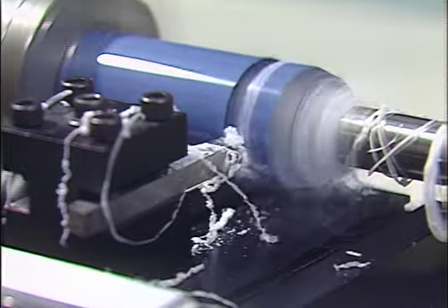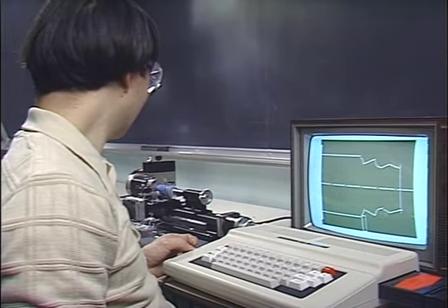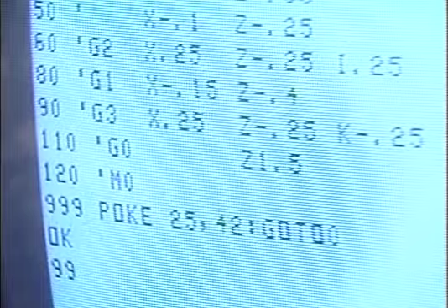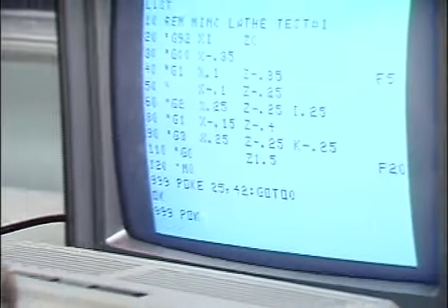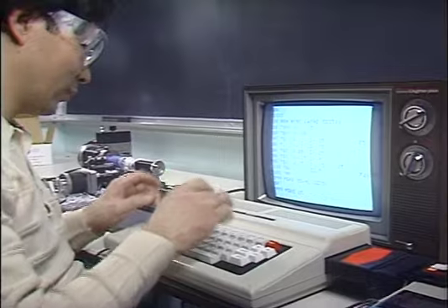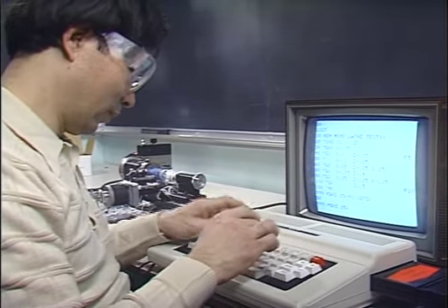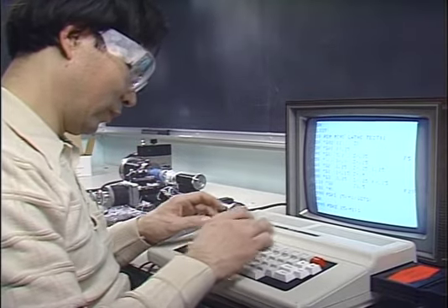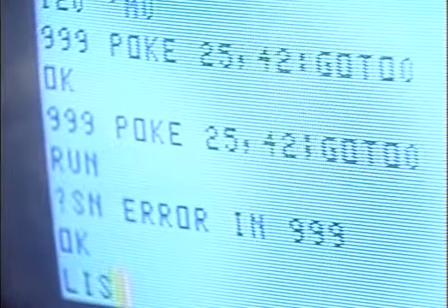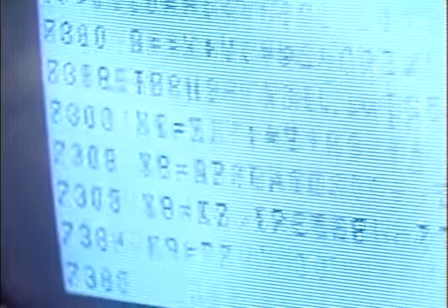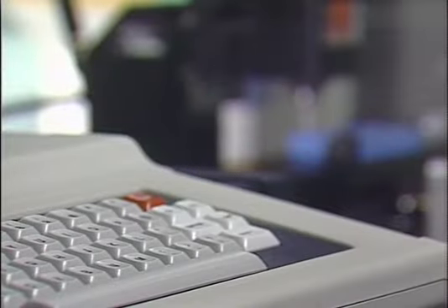The computer translates the part program into digital signals that are fed to stepper motors on the machines. The stepper motors control the positioning of the cutting tool with respect to the stock. The computer supports additional functions such as offline programming, program editing and verification, and links with CAD databases to allow automatic program generation from part geometry. Also possible are smart editor programs which check part program statements for syntax and logic errors prior to attempting execution. The part program may be executed on the machine tool or stored on tape or disk for future use.